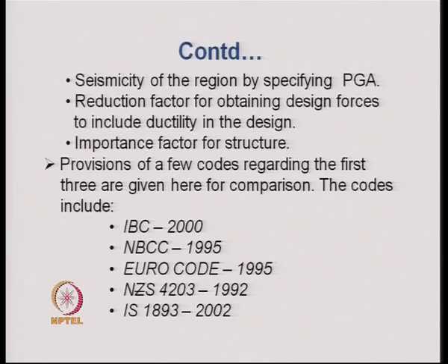The reduction factor is a very important criterion that is included in the seismic design of structures, to include ductility in the design. The basis for this is that we want the structures to go into the inelastic range at the design earthquake level.